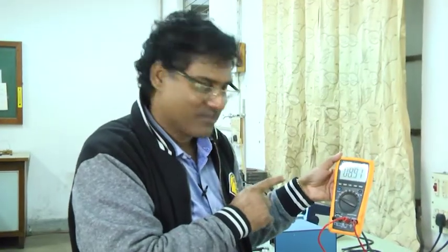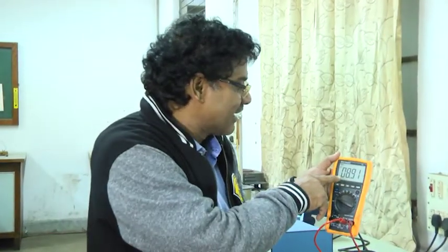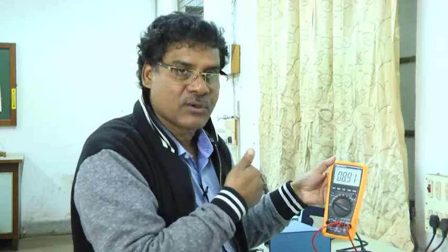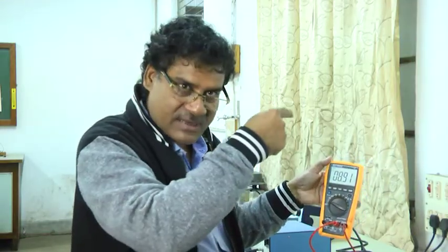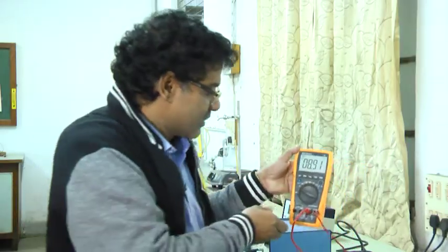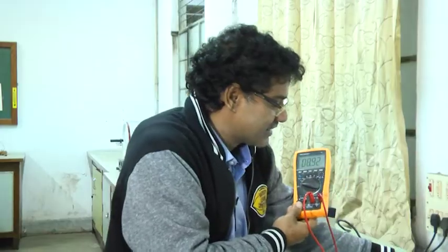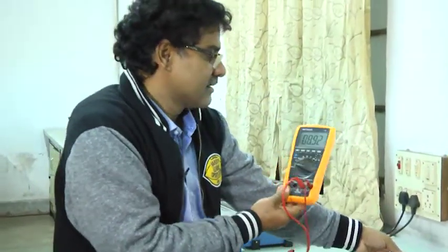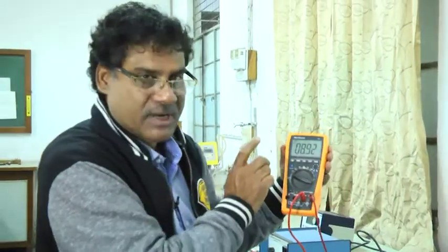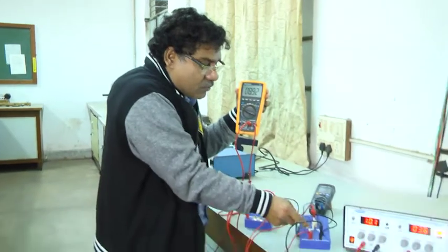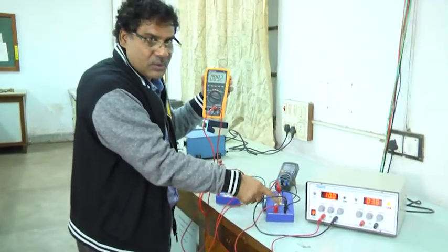So then you see how this is discharged. For voltage, what we have seen is that it will discharge exponentially. Current also discharges exponentially, but the current will be negative. Look at this: it's a positive value, and this also is a positive value. Now let me connect this switch to position 2.